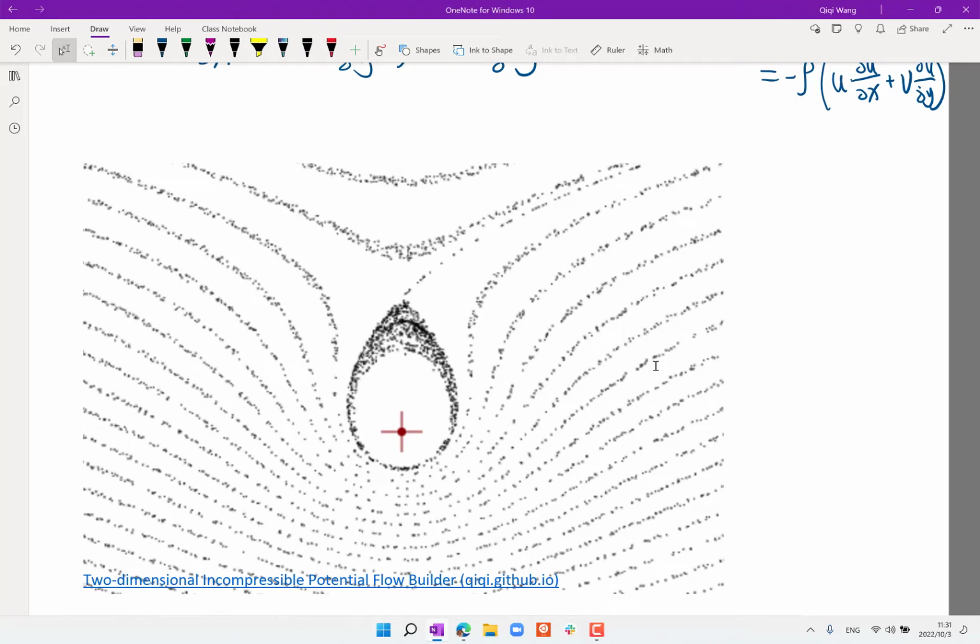And also it's potential flow, right? So we have Bernoulli's not only along streamlines but across streamlines. That means you know the pressure here is what? Very low, right? Because the flow is very fast. The pressure here is quite high, right? Because the flow is almost stagnating.